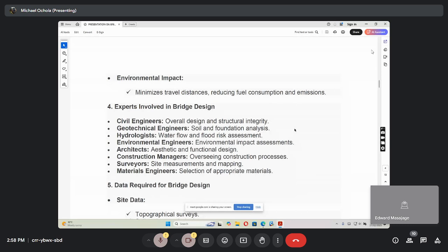So if you design a bridge for 100 years and corrosion just gets in within 10 years, that means within another 10 years, so 20 years, you see your structure failing. You see discoloring, spoiling, and debonding. There will be no bonding between concrete and steel, because corrosion is setting in and progressing and affecting the function of the steel, which is important in providing tensile property to concrete. So that is why you need a materials engineer on your side.